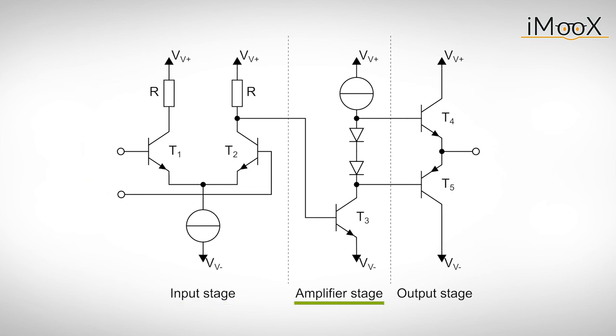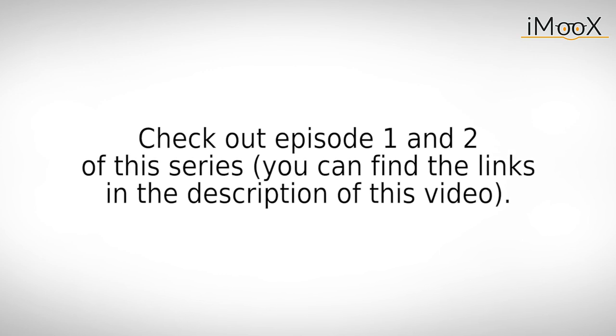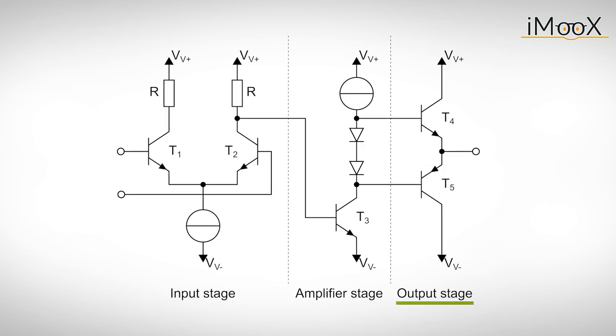The amplifier stage with its high voltage gain boosts the signal coming from the input stage. If you want to know more about transistor amplifiers, make sure to check out our other videos. The output stage allows the operational amplifier to source and sink large currents at its output while maintaining its output voltage.